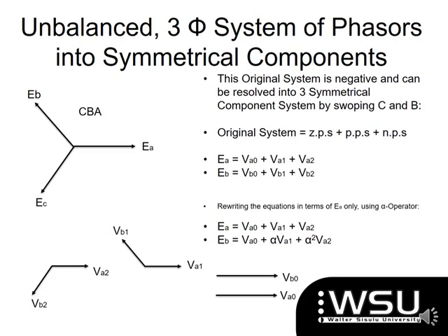And so therefore, if I'm writing now my EB, you can see that I now start in the middle because that's what I've now made my positive phase sequence so that it now follows the CBA sequence. So my positive phase sequence in this case is not what you know as your positive, but it needs to follow that CBA sequence. So that becomes my series 1 instead of looking at it as your positive phase sequence. And then my series 2 will now be the opposite, okay? Originally, where it would have followed what we would have called a positive phase sequence.